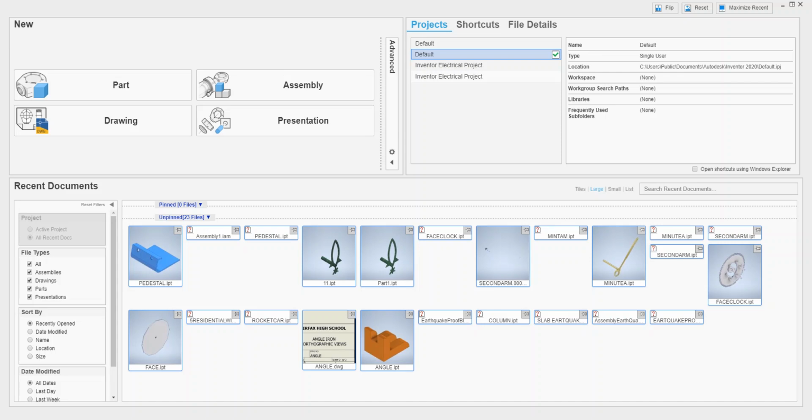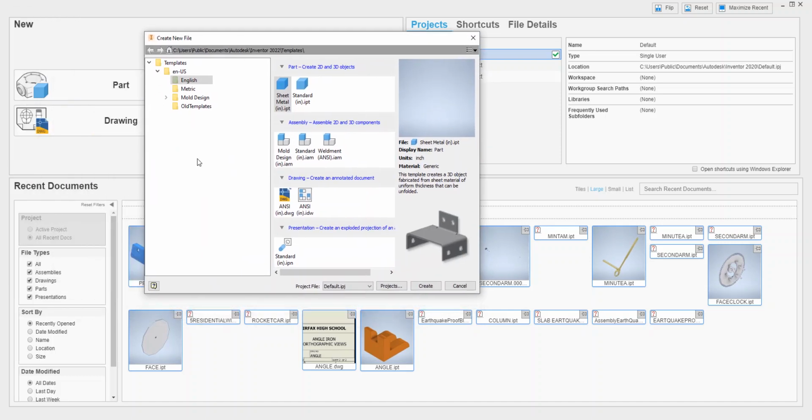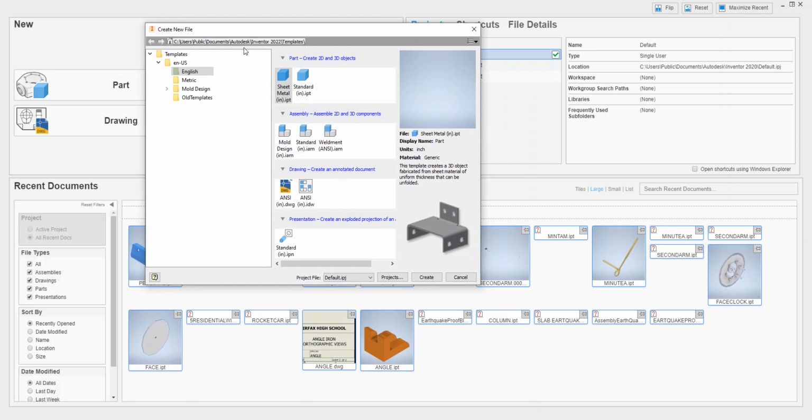And we're going to start Inventor as usual, making sure that the part drawing in inch system will be started. There are multiple ways to do that. You can go to the New button on the top after you start Inventor. Click on New, and you will have a dialog box. Within the dialog box, you choose EN US or English US version, and click on the folder, select the English option. Okay, we can have a metric option.